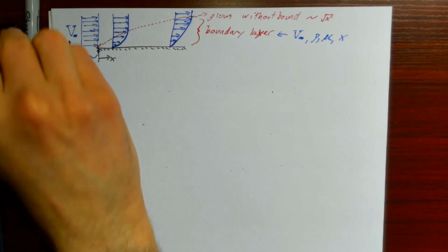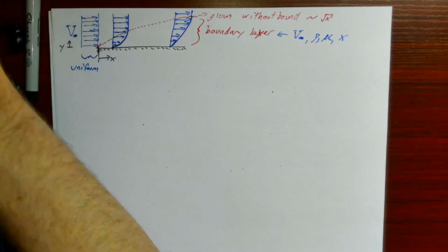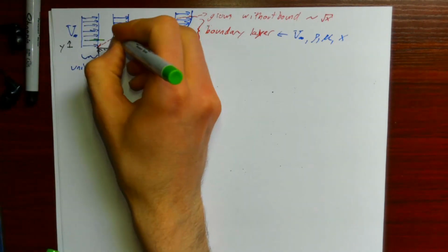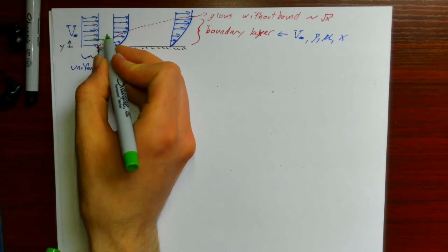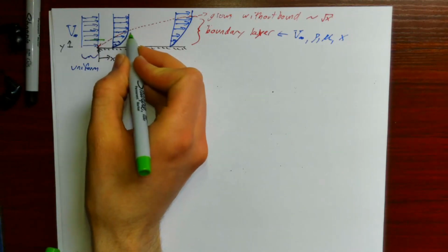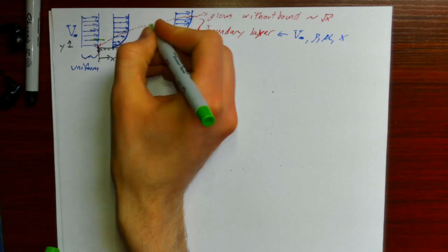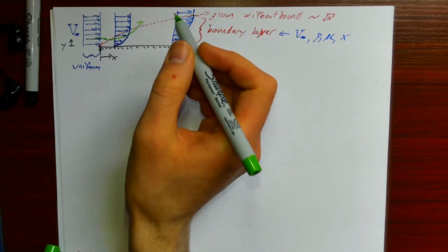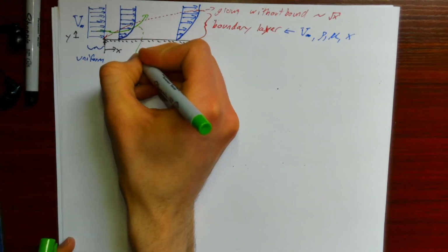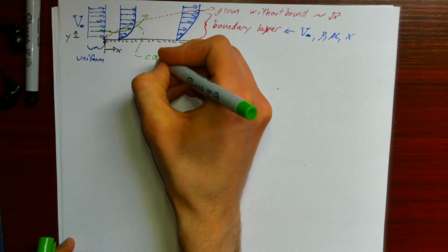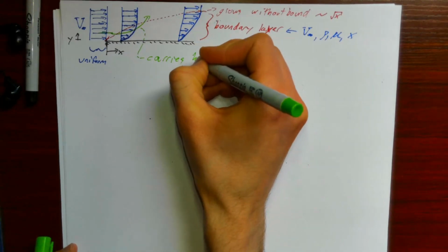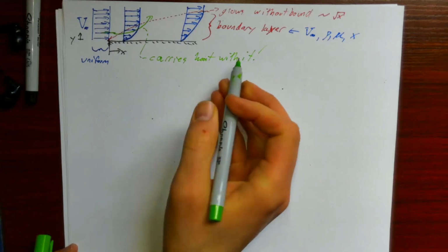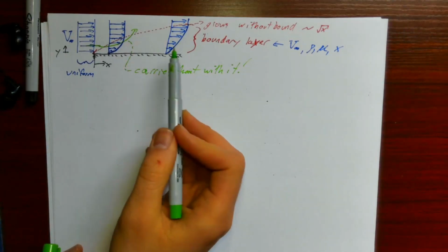Well, you can imagine if I have cold fluid coming in, with the growth of this boundary layer I essentially have more velocity coming in, more fluid coming in here than going out here, so the growth of this boundary layer actually steers some fluid out of the boundary layer. And the fluid that gets steered out of the boundary layer carries heat with it. So we don't just care about this from a hydrodynamics perspective.